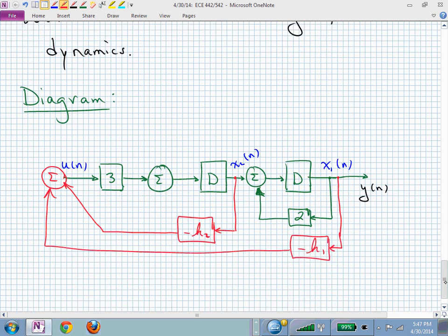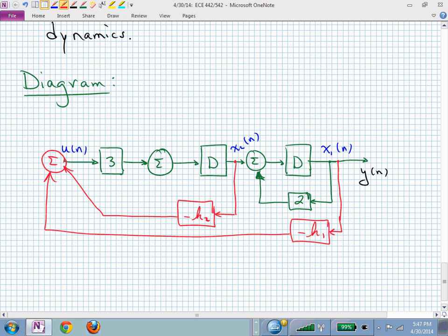Here is a more specific block diagram of what we're trying to accomplish. This shows you in a block diagram what full state means in this 2x2, or second order, case. The green should be the block diagram that we derived last time. And we labeled the states to be the outputs of the delay blocks. Here I'm simply saying, let me call that rightmost delay block x sub 1, and the next delay block will label its output as x sub 2. Those are now my 2 state variables.